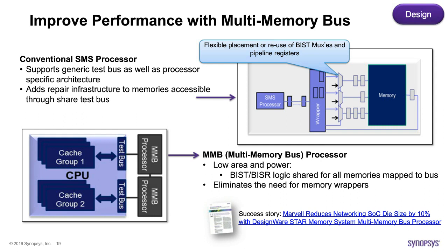Like you do it for memories, you can do it also for processors. Certain places where the data path is critical in terms of timing, and then you can put your BIST muxes in order to optimize the speed, that is the normal functional speed of the processor, and thus have your self-test algorithms, self-test coverage, and repair coverage meant with smallest impact in terms of performance.